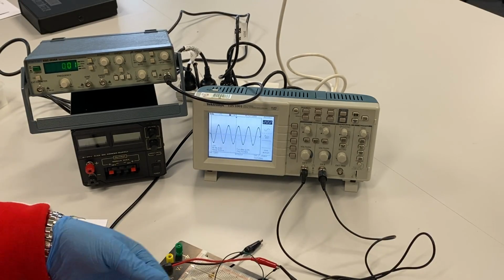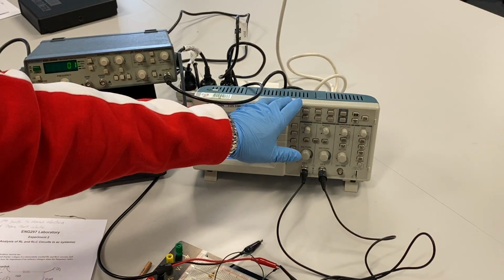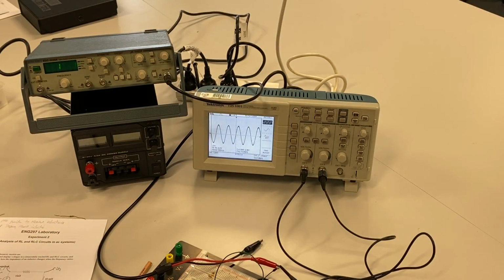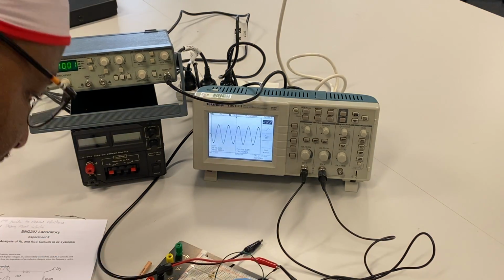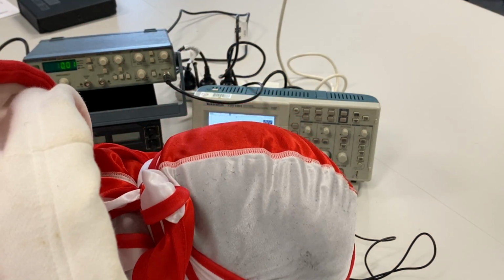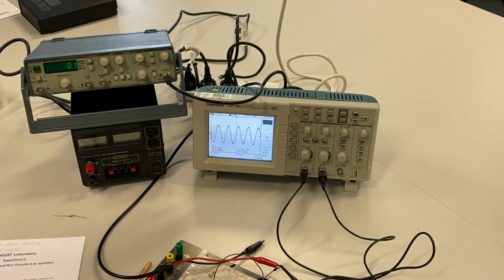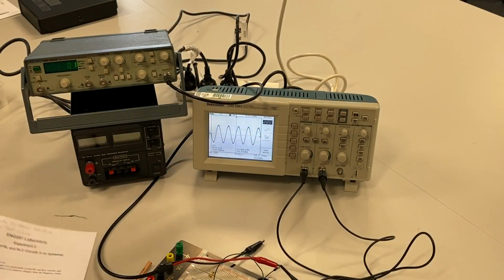Then ground, see, I will always advise this. Grounds of oscilloscopes, inside this oscilloscope, they are tied together. So try to put grounds, because some circuits, when they become complicated and you connect grounds on different sorts of nodes, you cancel out one of the signals. So try to put the grounds at exactly the same node. So my ground is where this other leg of the inductor is connected, right? Where this leg of the inductor is connected, that's where my ground is.